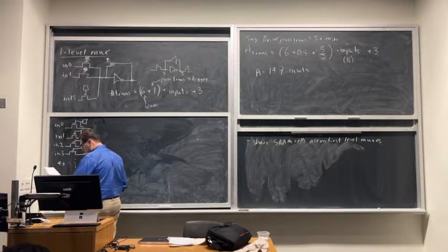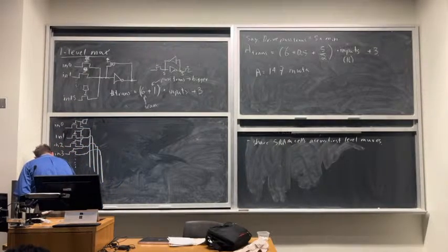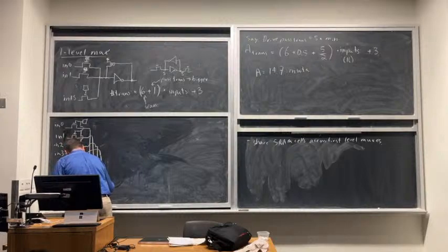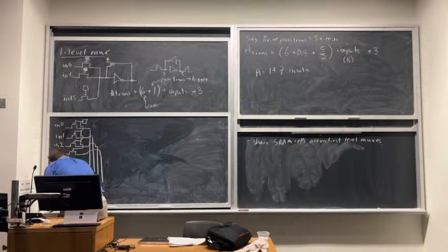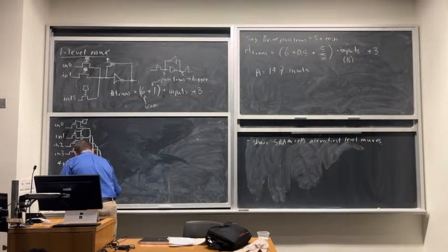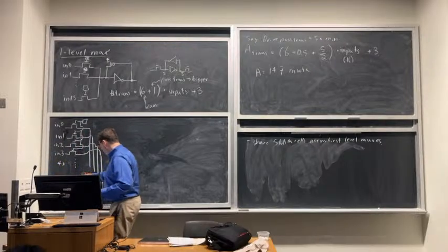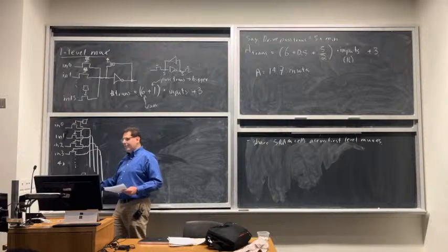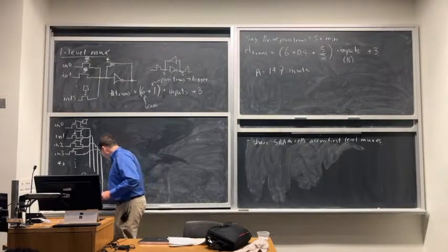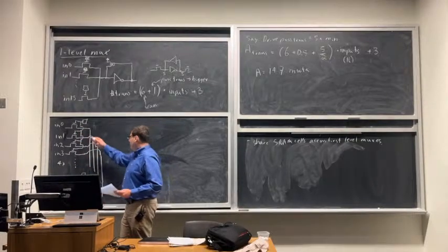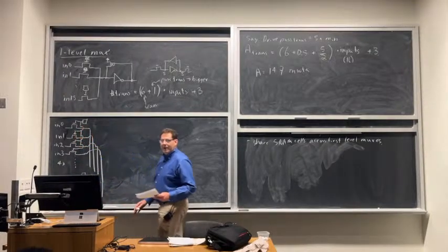So I'll show the bottom of that structure. Okay, so here's input 14. Here's input 15. Okay, so this SRAM cell actually also controls 4 pass gates. I'm only showing the last 2. And so I repeat this whole structure 4 times. 4 groups of 4 pass transistors, each controlled by 1 SRAM cell.